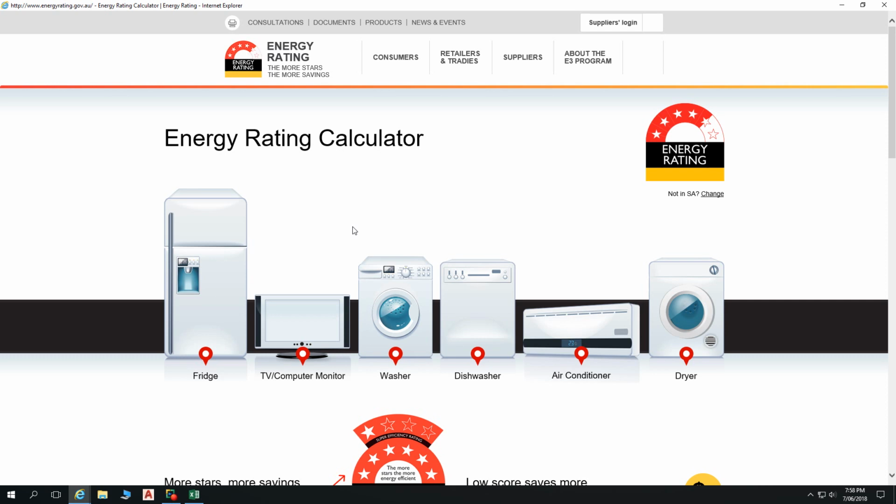So what you'll have to work out for the assignment is how many square metres you're lighting up, so give the total square metres, and then work out what lux you'll require. That will be done by looking at this table: do we want 240, do we want 320, do we want 400? Work out that lux requirement.